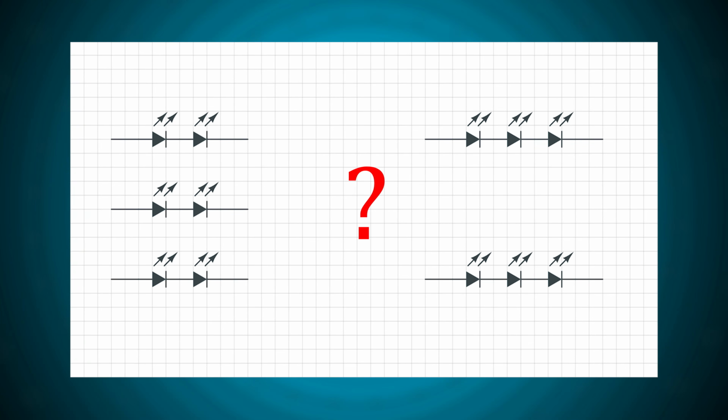When wiring LEDs, you have to choose a connection scheme which yields resistors of lower value. Why is that? Well, because when you wire a resistor in series, some power is dissipated into heat. And the larger the voltage drop, the larger the power dissipation.